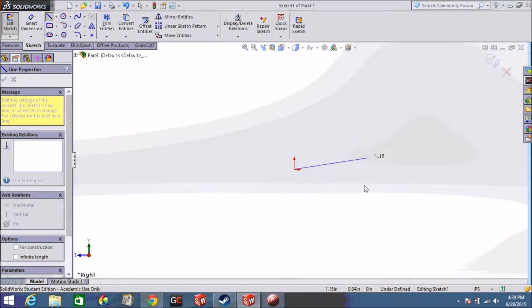I click at the origin, and now I have to choose a second location to click to create the endpoints of this line segment. So as you can see, I can move around and put it wherever I want. However, if I approach 90 degrees, it'll lock in. So that's how you can assure that the lines you draw are at right angles to each other. If I do this, locked in place. Now I have two locks. I can lock this way at another 90 degrees from the initial starting position, or 180 degrees up here.